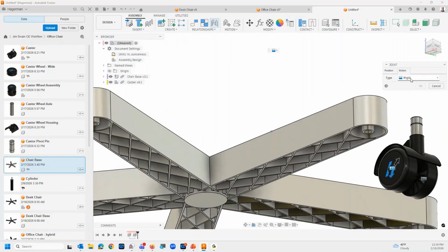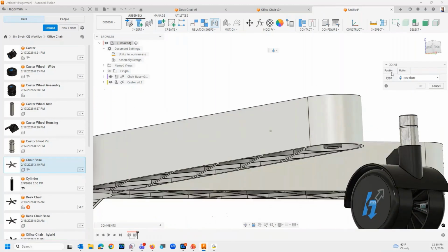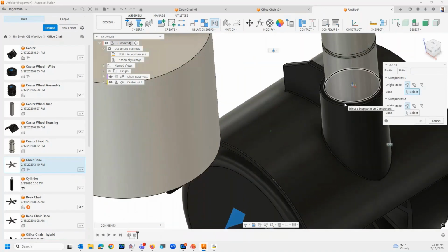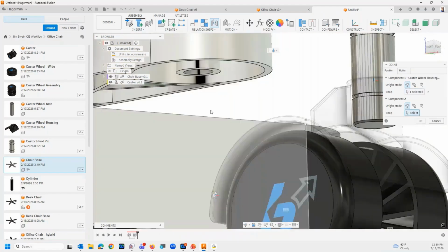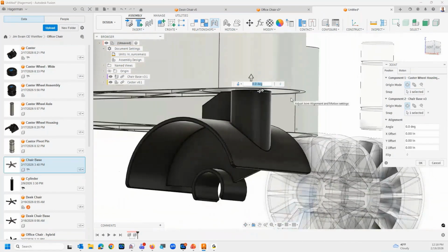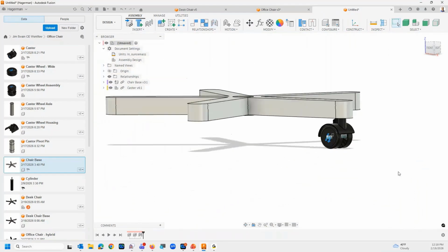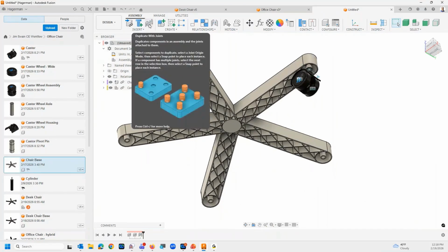Let's see, I'll set the joint for Revolute. Go back and grab that top ring there. There's a little fillet on there, and I don't want to grab the fillet. I may have anyway. That would be Murphy's Law as applied to presentations, but we'll go ahead. All right, so that's grabbing it there. Everything snaps into place. Now, instead of doing a pattern, relatively new, duplicate with joints.